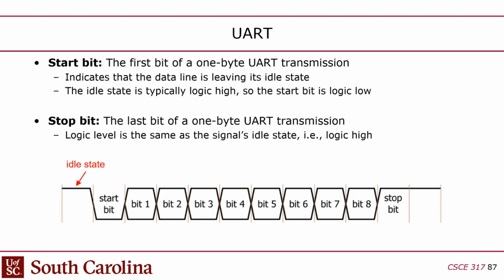And so how does UART address that? Well, it does it by using a really slow clock, which reduces the likelihood of that happening. The clock rate in I2C and SPI is megabits per second. This is kilobits per second, right? But it also has a parity bit, which I talked about when I was going through the quiz. There's a parity bit that detects errors, and it's also used for that purpose. This is an error detection mechanism. The parity bit, however, is optional, so you don't always have it.